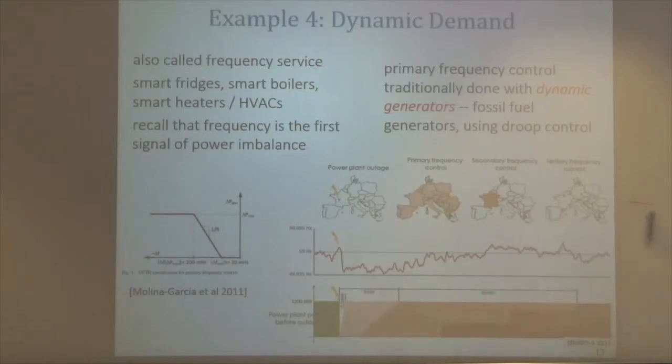That may involve demand response, and then those reserves need to be brought back to their nominal values because another incident might come. So then you start what is called tertiary reserve, which consists in calling other generators, starting, for example, a gas turbine of some kind. And here the gas turbine might be in a foreign country if France is buying energy from a foreign country. This is how grids work today.